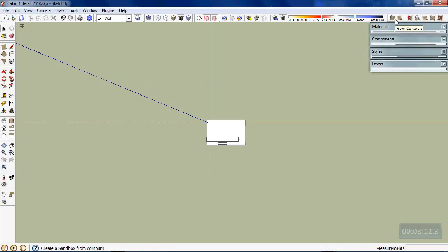Now I'm going to show you this one from scratch to start with in this particular case here. I'm going to click Sandbox from scratch, and what I want to do straight away, you see down in the bottom right hand corner of my screen, the grid spacing is set to every 5 meters. I'm going to change that to a 1 meter grid, and then I'm going to come somewhere way out here, way in front of the building, and come through. I don't think that 1 meter grid worked. I'm just going to escape out of that and come back again. Grid spacing should be 1, 2, 3, and press enter.